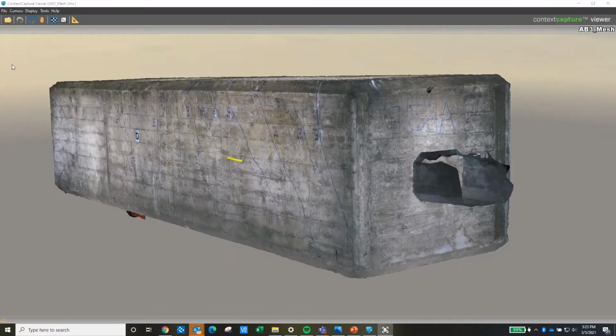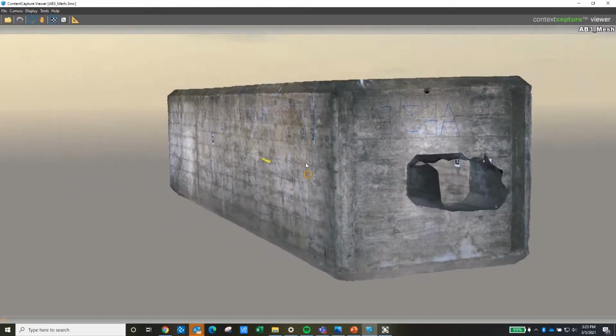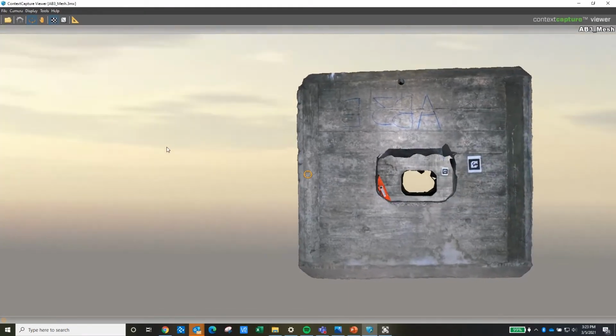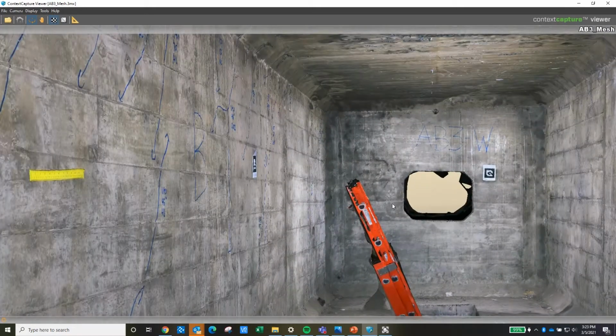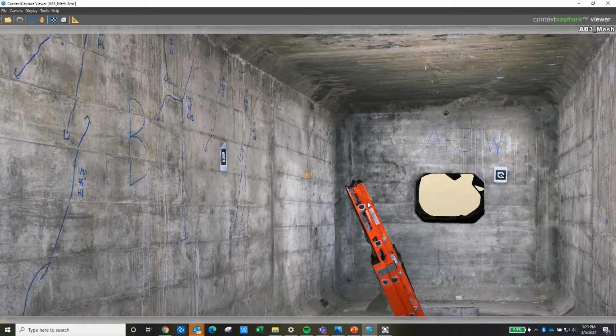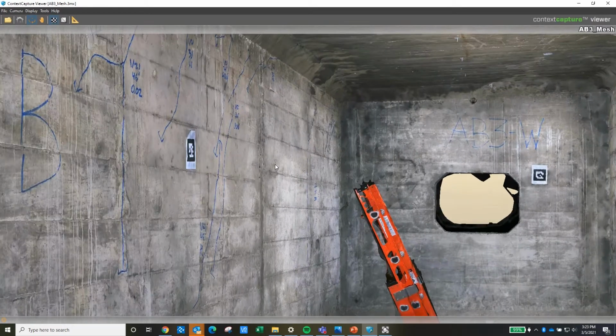This is another digital twin for MnDOT where we're doing inspections of the insides of box girders. And so we go in there, we mark up the walls with the cracks with marker, and then we go inside, we collect images of the inside, and we post-process those into this 3D model. And so what it saves us is first we have a really accurate model that anybody can go look at and understand what it looks like in there.